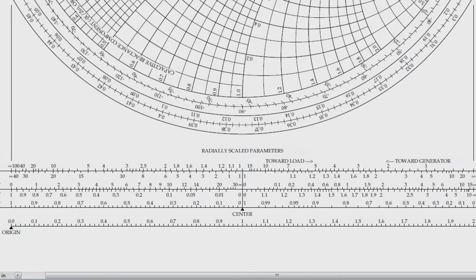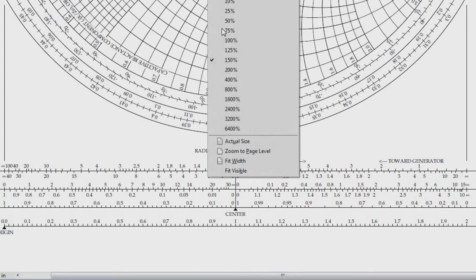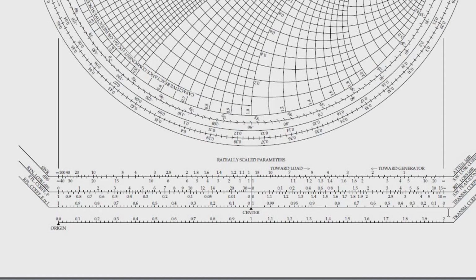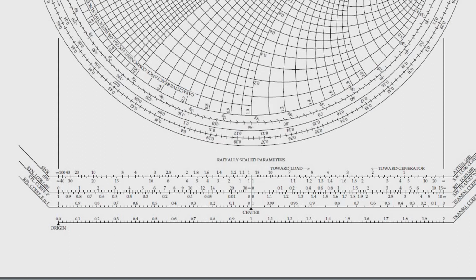On this left hand side we saw, when you move to the right hand side, by decreasing the size, here also the transmission coefficient exists, transmission coefficient and SWR, and here also some parameters exist. For those parameters we are going to use all these scales. Here we are going to use the SWR scale and the reflection coefficient scale. Then we will move in the upward direction.